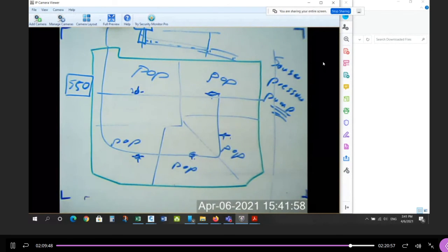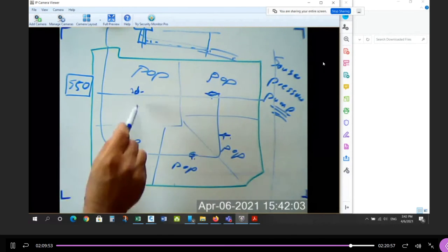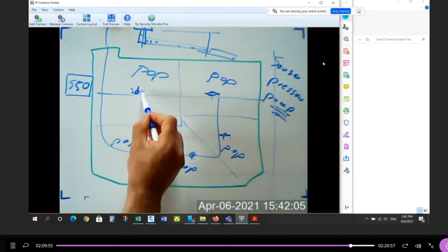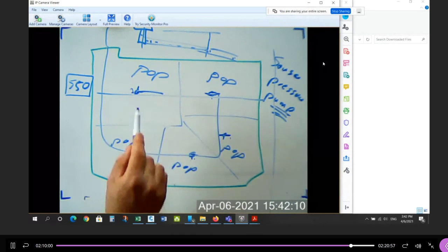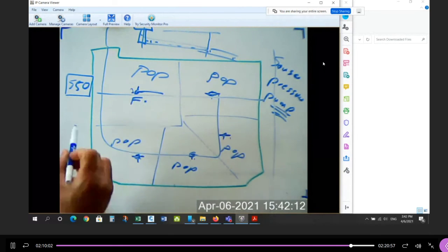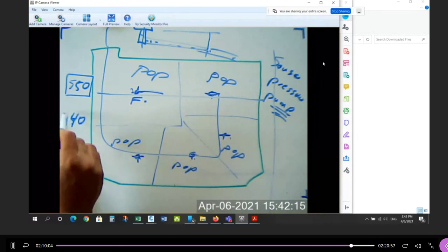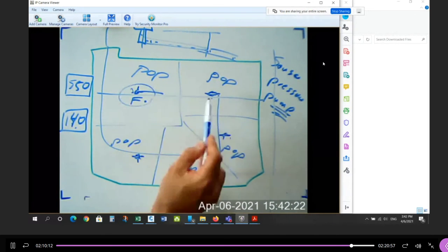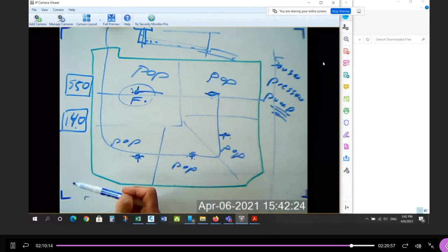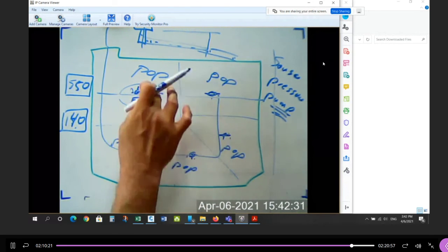Then it systematically goes through your model and assumes there's a fire flow at each hydrant. When you start to draw fire flow on each hydrant, the pressure in the system drops. So if there's a fire happening here, make sure that you have at least 140 kilopascals pressure at all the other locations. So model a fire here. What's happening at these four locations? Are these all greater than 140? If so, it's good. Then it goes to the next hydrant.